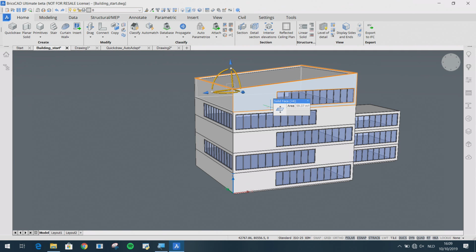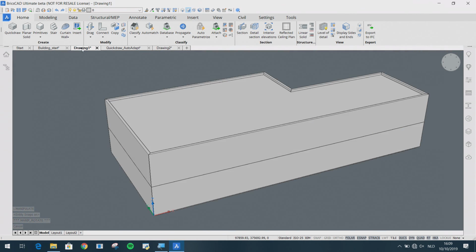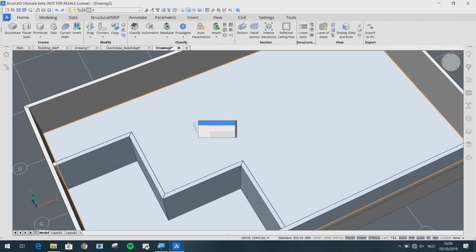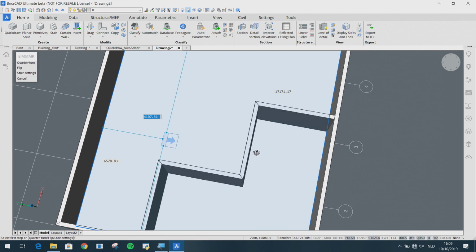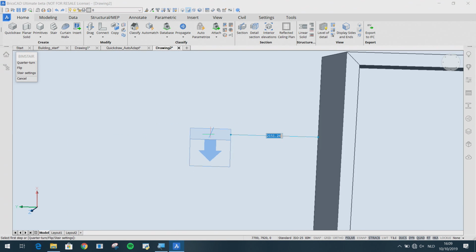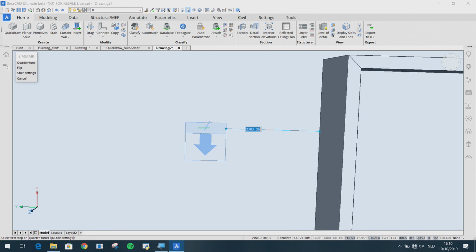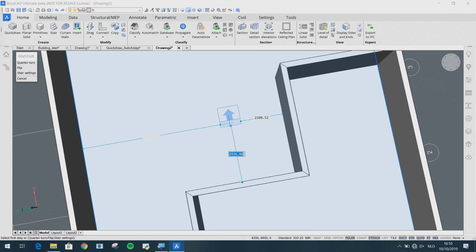Of course, we have a free modeler. We can model anything and model a stair from scratch, call it a stair, classify it as a stair actually, and it will have the correct IFC properties of a stair. But we also created a new tool, which you already saw in action, the stair tool, to help facilitate the layout of your stairs. You don't have to do the calculations about the number of steps and tread length and everything. The tool does this for you and satisfies all restrictions imposed on stairs.